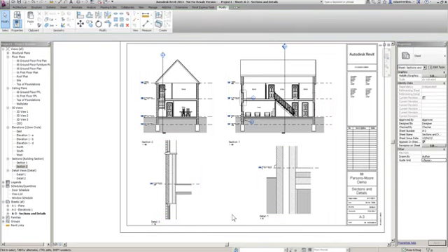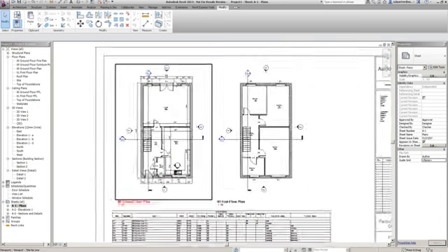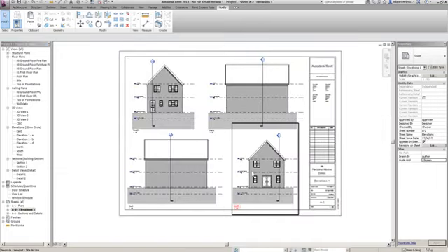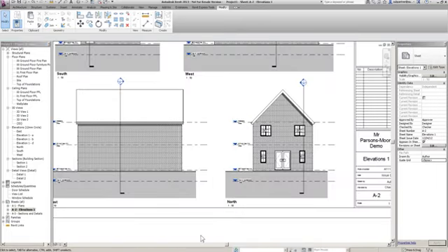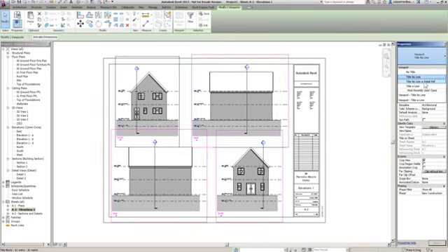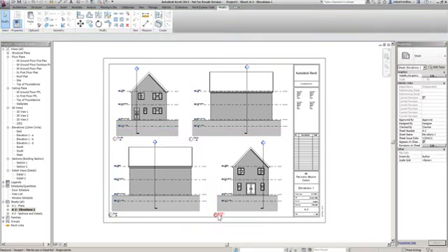There we go. Now, a lot of people when they first start putting sections on wonder why the information in the bubbles doesn't fit in. Basically, the information in the bubbles fits in once you have placed the section, elevation or detail onto a sheet. Let's look at my ground floor plan. That section there: drawing A2, detail number 4. When I say detail, I've turned it off by accident. We need it to have that number there as well. It has this detail reference on it.